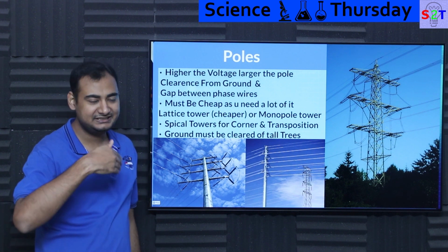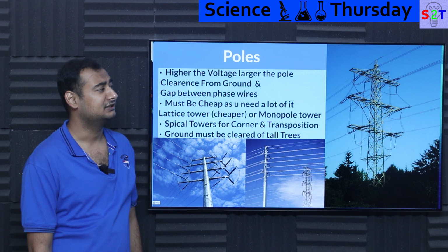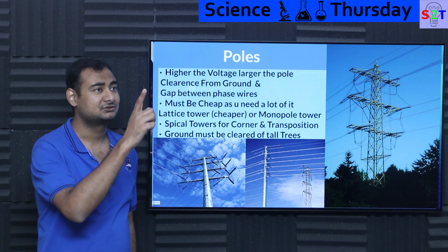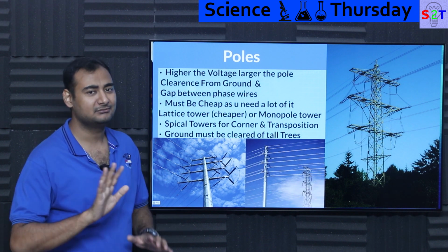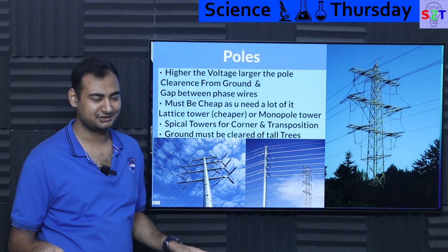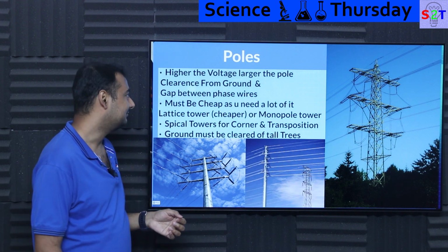That increases cost. And you can easily guess, there are some engineers who are so good, they look at the height and it's like, yeah, that's 135, that's 230, that's 500 kV. Oh, that's 1200. Again, I'm reasonably sure most of you can just spot 1200 kV because it would be so tall. So you have to figure that part out.